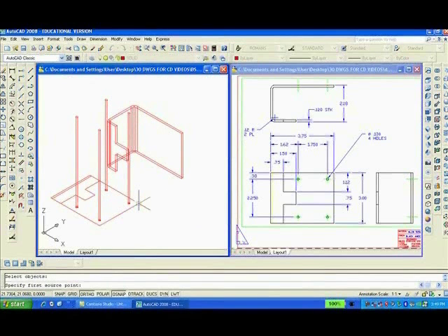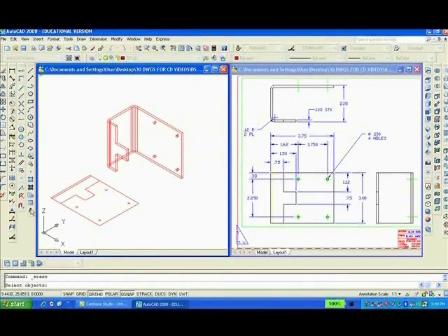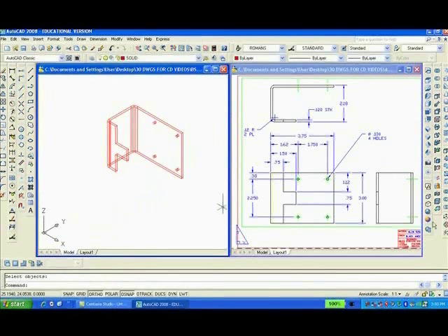I'm going to go from there to there for the first point, from here to here for the second point, and from the midpoint of here to the midpoint up there. Then all I have to do is to subtract from that, enter these 4 cylinders, and the holes should appear. That's one way. I'm sure there's other ways of doing it. Now I want to erase that and see what this object looks like, this bracket, sheet metal part.